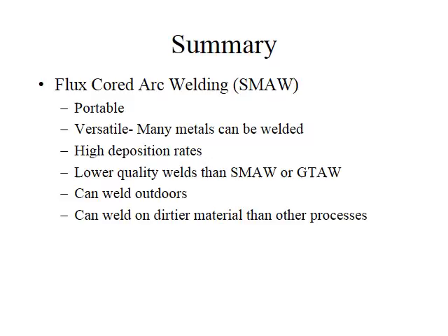The two different methods are identified by self-explanatory names: flux-cored arc welding with self-shielding, meaning without supplemental shielding gas, and flux-cored arc welding with auxiliary gas shielding, with supplemental gas shielding. Flux-core arc welding without gas compares somewhat with shielded metal arc welding in that it can tolerate worse working conditions than a process that requires auxiliary gas shielding. It is less cumbersome because of the absence of gas containers, and it can tolerate drafty conditions. Both types of FCAW enjoy great popularity in the steel fabrication business.